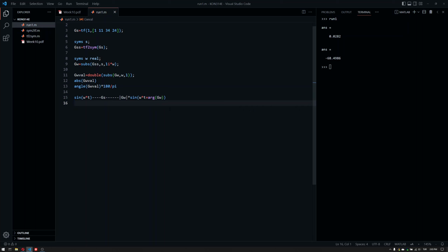But if you have some road disturbance, some aerodynamic forces, etc., those will have their own frequencies. Then you're trying to come up with the best setup that will reject the disturbances and attenuate the noises in certain frequency ranges, but still track the input in some frequencies, probably low frequencies.